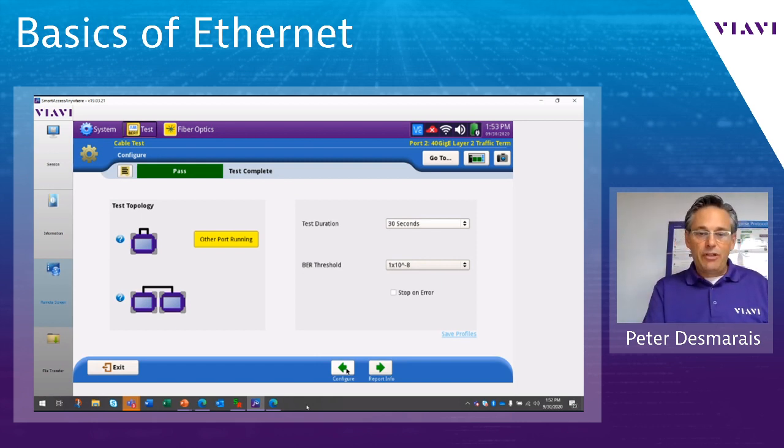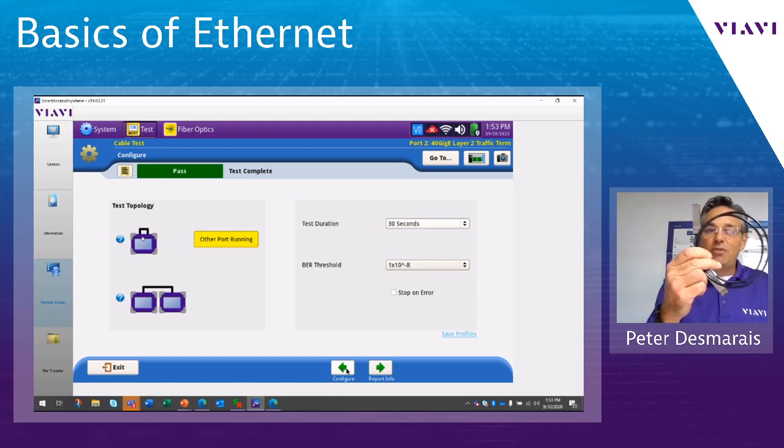In the T-Bird 5800, we've added a test suite that automates the process of actually testing these. I know I've been on site, and we see guys have buckets of these things that they just pull out of the network and throw out because they think it's a bad AOC or DAC cable. This allows you to actually test it. Two ways of testing. If you've got a 5800 that's got dual port, you can loop the cable back onto itself. That's good if I'm just testing a short patch cable. If you're testing a longer cable across the data center, then you would use two devices, one on each end, because obviously you can't loop it back to itself.